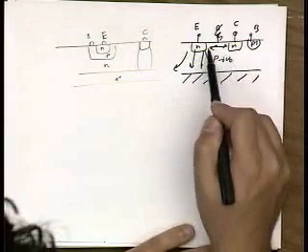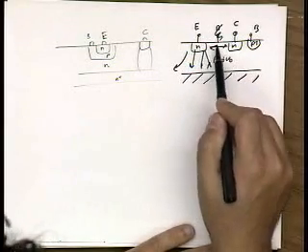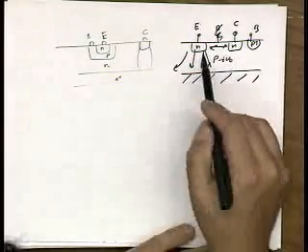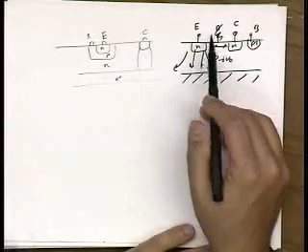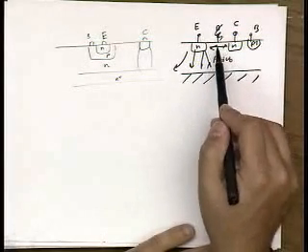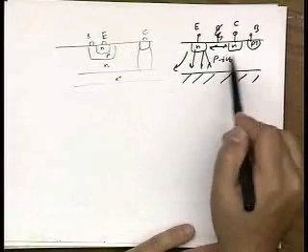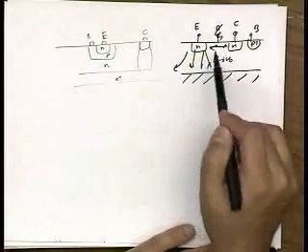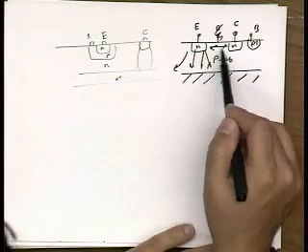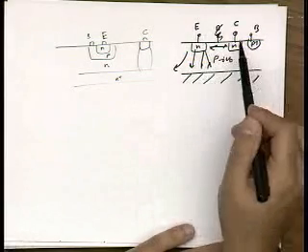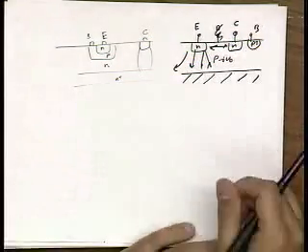What we really want is to dope this optimally. We won't go into the device physics, but you want to dope it optimally so that you're injecting more electrons than holes, reverse injection, and then you want to collect all those electrons. So it's not just the distances, you also have to really have the right doping profile. And there are other issues too.